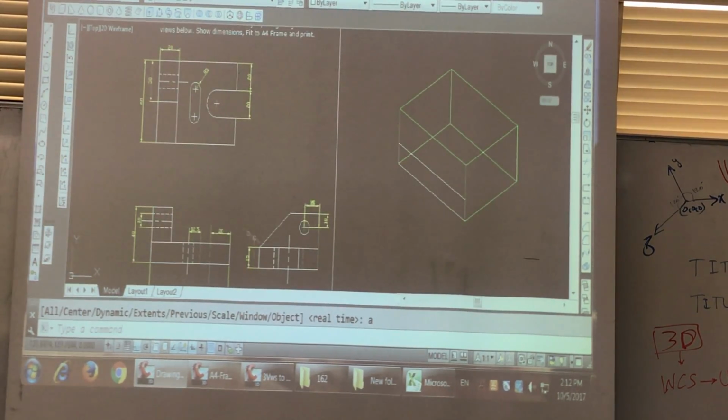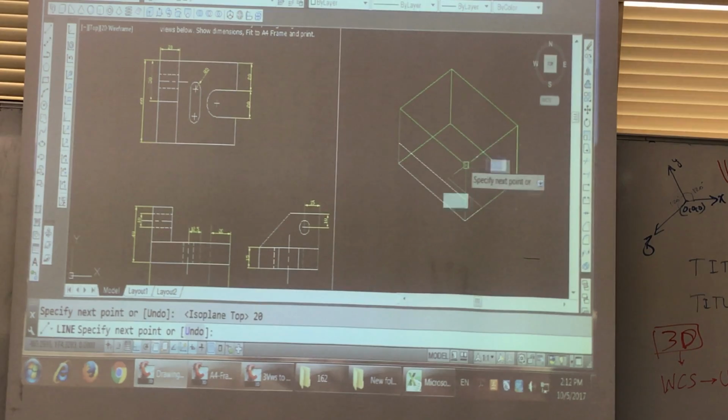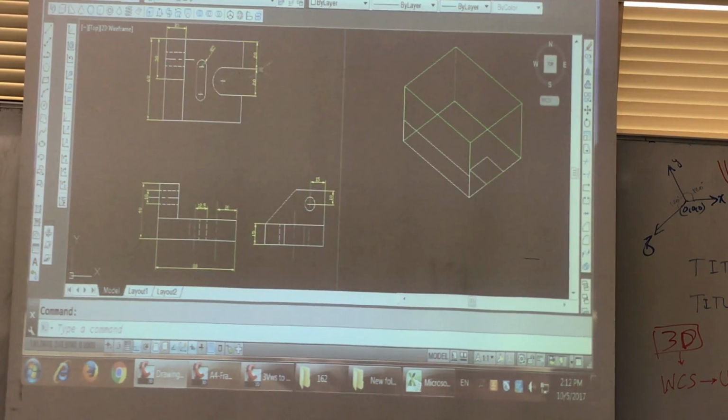So you know these three boxes together, we will combine over here. So I will take a line, start from here, go in this direction, F5, this direction, 20, 20. Then I will go in this direction, 20. Then this direction, 20. Then this, 20. Then here, 20. See, what I am trying to produce is this shape. How much is this up to the semicircle? It is not given here, but it is given here as 20. So that's why it is all 20, 20, 20 like this. All dimensions are 20 in this particular exercise. In another exercise you may have different dimensions.